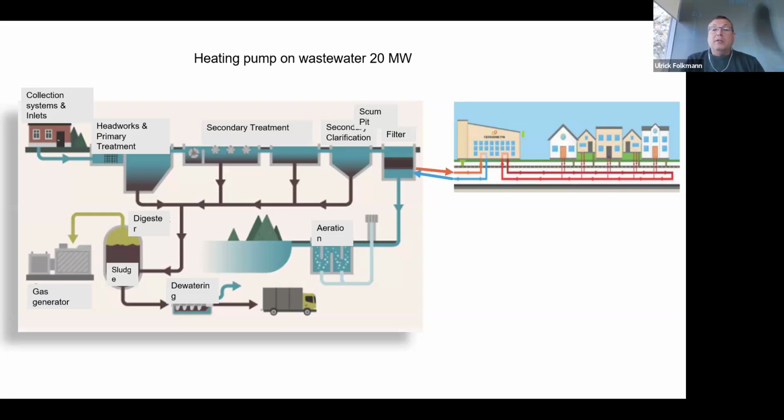And as Nancy also told us about, the water has a very stable temperature, so it is a very good idea to take this water into the heat pumps. Today we have a COP around 5 and sometimes up to 6, where we get 6 times more heat out of the pump than the power we put into it. So put 1 kilowatt in, and you will get 6 kilowatts of heat out of the system.